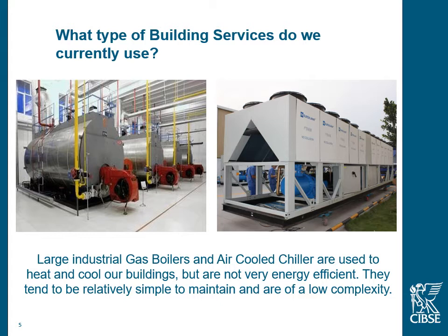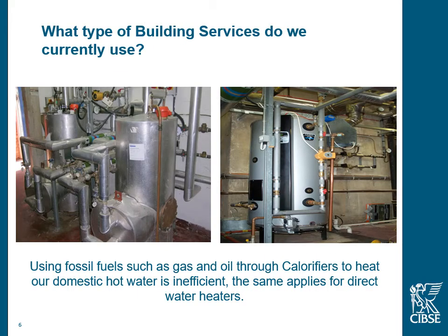The unfortunate thing is doing that is quite difficult, especially with the chiller that's shown in the photo there. That's an air-cooled chiller, and trying to recapture the heat from an air-cooled chiller is nigh on impossible. What we could do is use a water-cooled chiller and pass that water through a heat exchanger in our hot water tank there, and transfer the heat via a heat exchanger. Obviously, we have a big demand for hot water. We need a dedicated hot water heater, as shown on the right there. But the one on the left could be using recycled heat coming from our chiller.